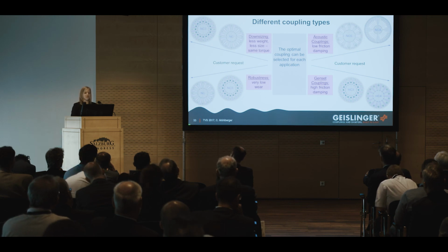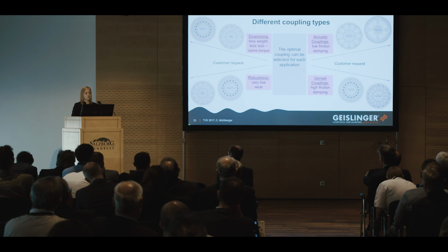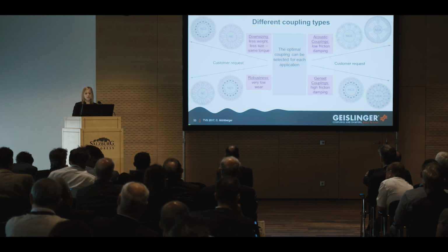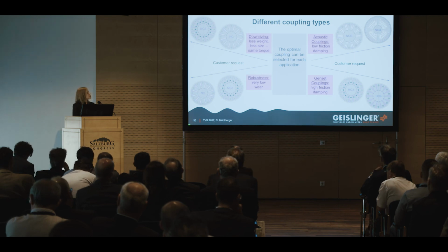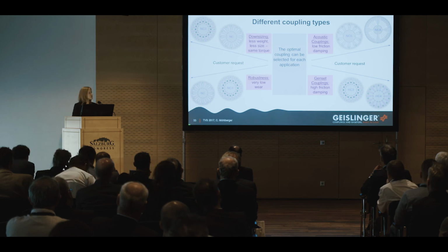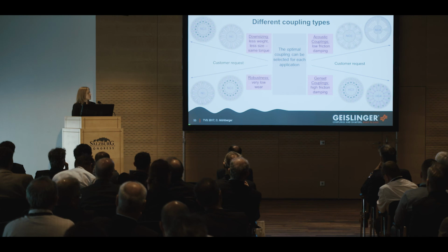So it is very important for us in the torsional vibration calculation team to know as much information as possible about the application, about its requirements, and about the customer's wishes, so that the optimal coupling, the optimal design and the optimal hydrodynamic damping can be selected. This can be done in terms of downsizing, in terms of acoustics, in terms of robustness.